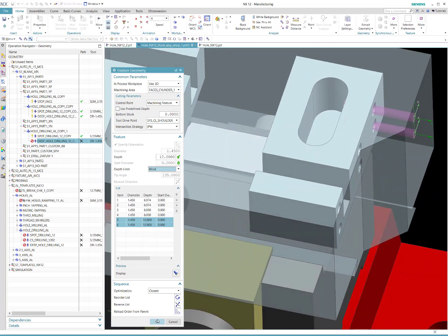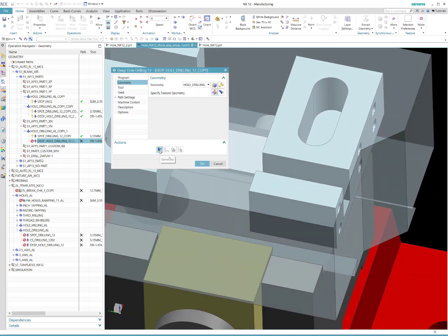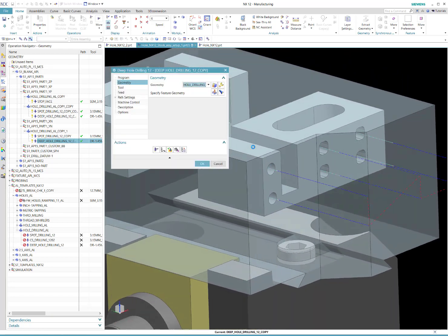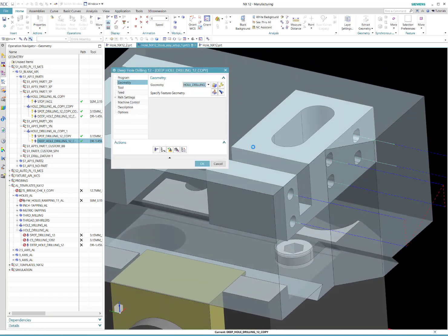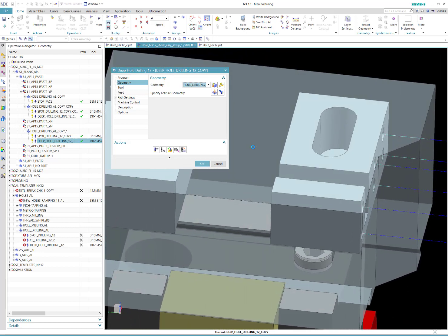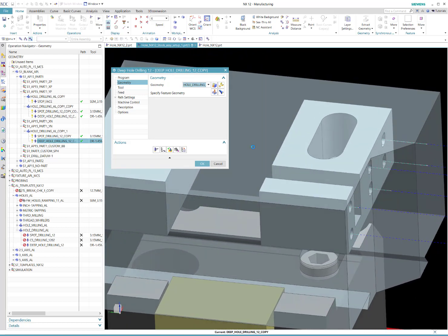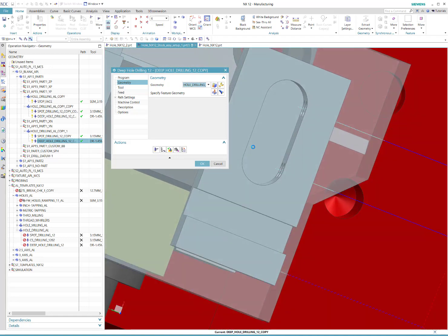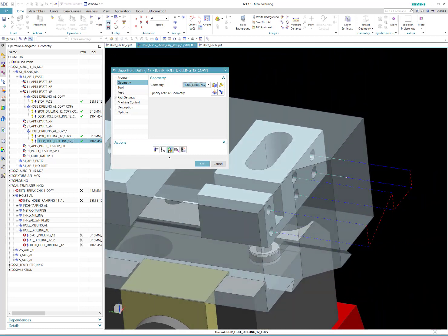Okay, I'm going to go ahead and accept that and generate. And without creating any extra geometry, I was able to have it recognize my unusual blank configuration. And like I said, even if I'd milled that down and roughed it to different depths or whatever, it would recognize the 3D IPW for starting the drilling and drilling that through.